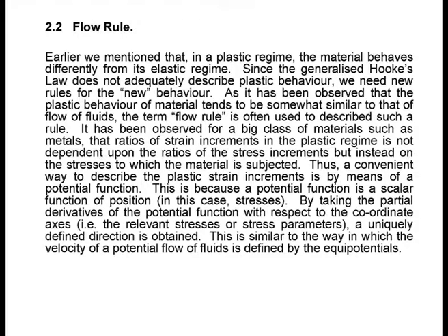Okay, the yield criterion tells you when you will get plasticity. That is, at what point will you start to get plastic behavior? Then the next question must be, after you get plastic behavior, how does the material behave? Do you still follow Hooke's law? You know what I mean? But in fact, I already told you that Hooke's law doesn't work, so it doesn't follow Hooke's law.